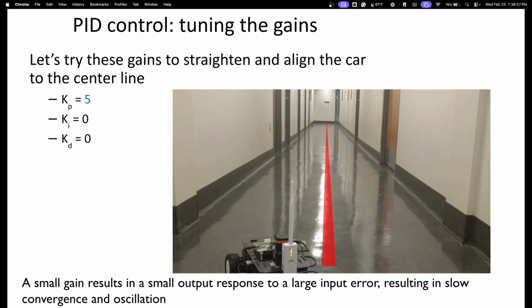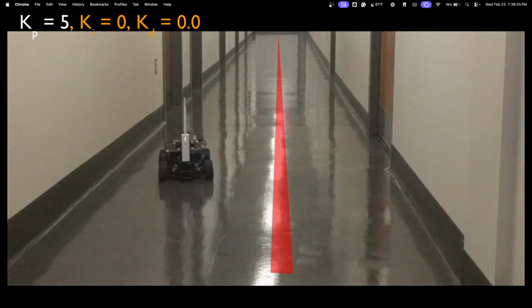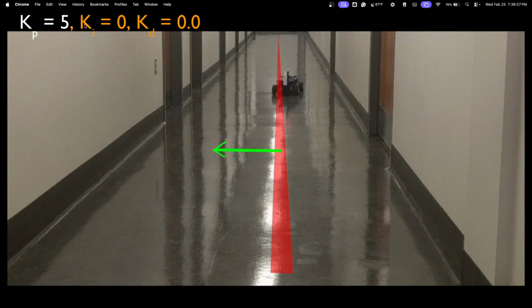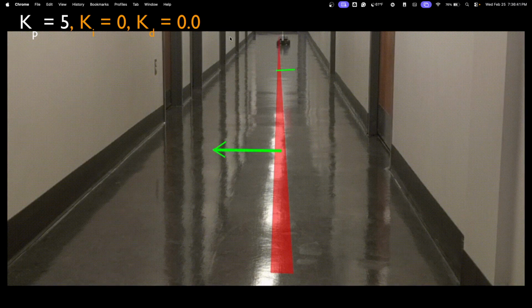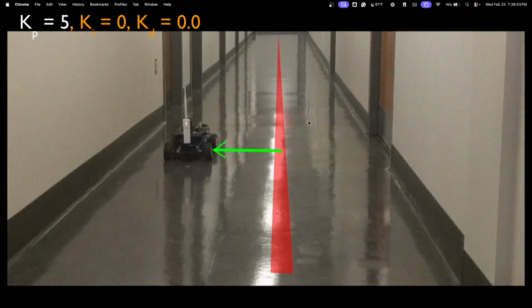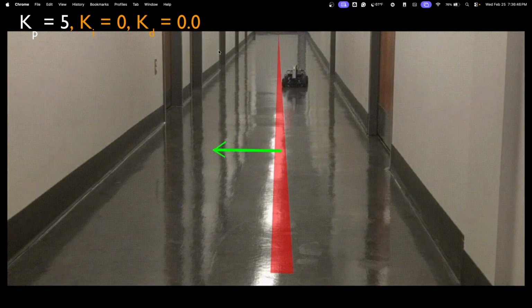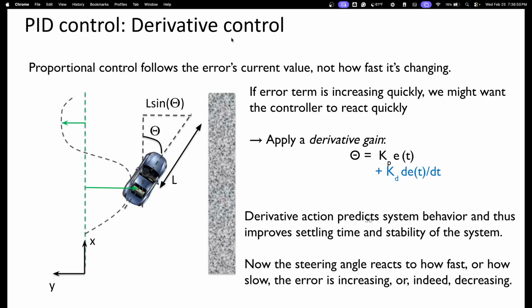And so this is an example of how you would want to fine tune your PID controller. As you can see over here, you have the P controller set to 5, and the vehicle will be oscillating a little bit. So obviously you don't really want that if you're racing, because you're losing a lot of track. Even if you're just navigating overall, you wouldn't want that.